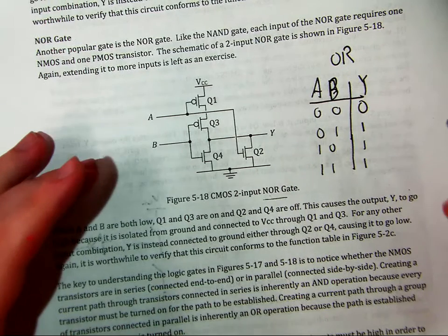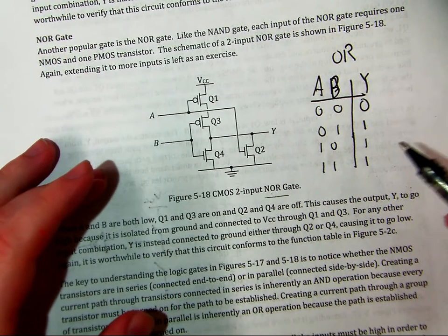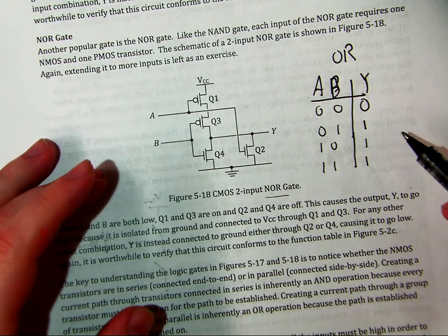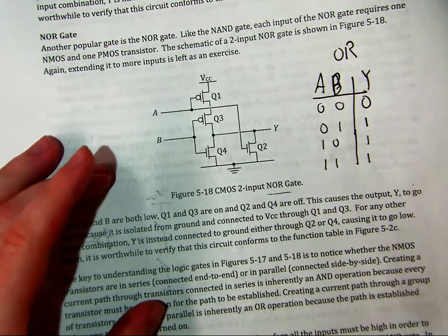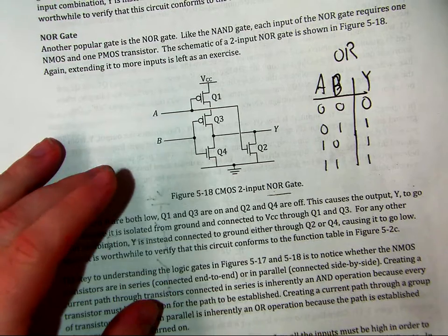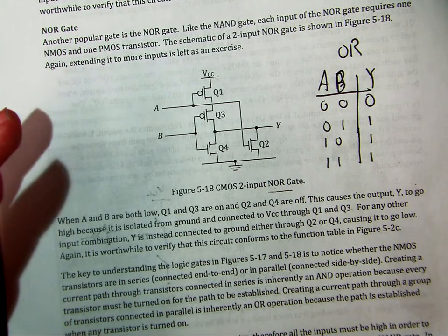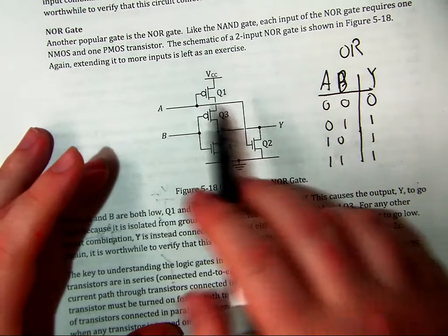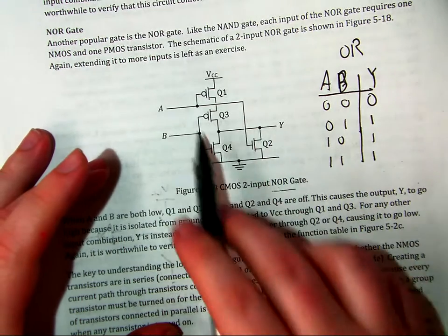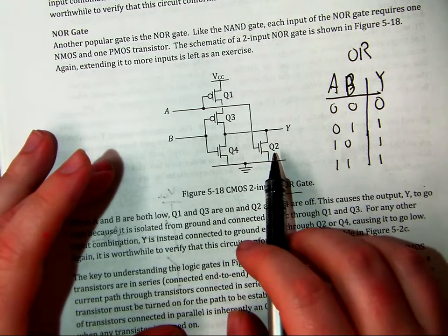If you need an AND or an OR gate, you build one of these and then just add an inverter. This is kind of why the NANDs and NORs are universal gates, because they only take 4 transistors to make them, and then to make an AND it takes 6.